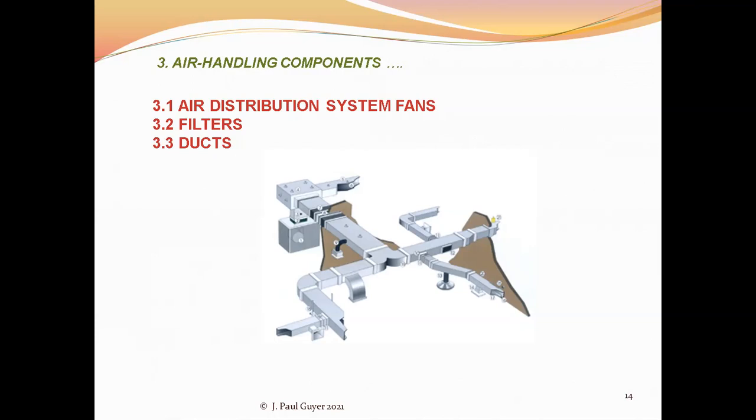And these components, typically they are the fan. That's the big fan moving the air throughout the floor or your entire building. And then filters, because filters are always part of the air distribution system for air quality purposes, to filter out dust and odors and things like that. And then the ducts themselves, and then the dampers are one of the tools you have to work with.